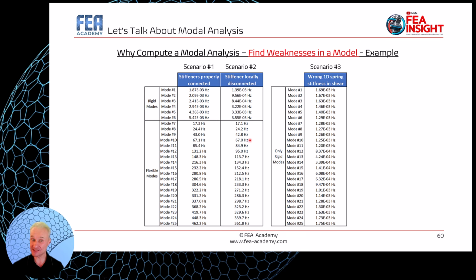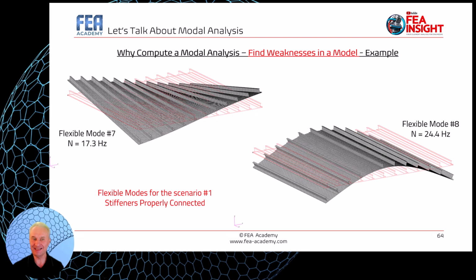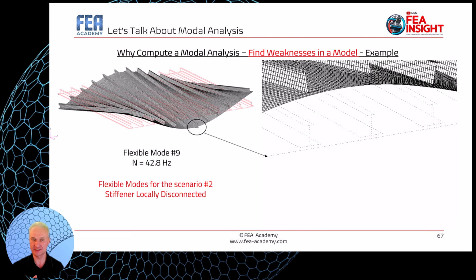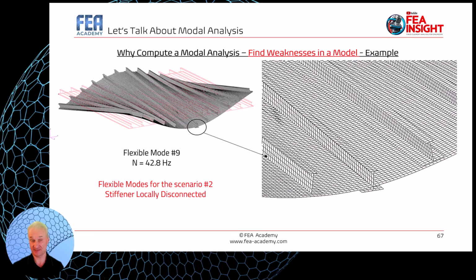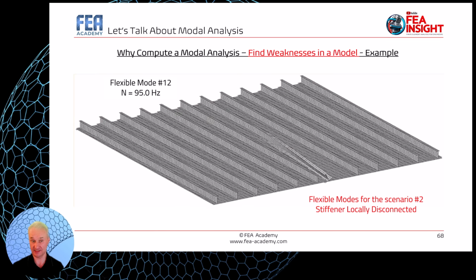So looking just at the natural frequencies, it seems that everything is correct. So it shows you that you absolutely need to plot, with your post-processing software, the mode shapes associated with the natural frequencies in order to capture this kind of problem. But you see the power of the solution.